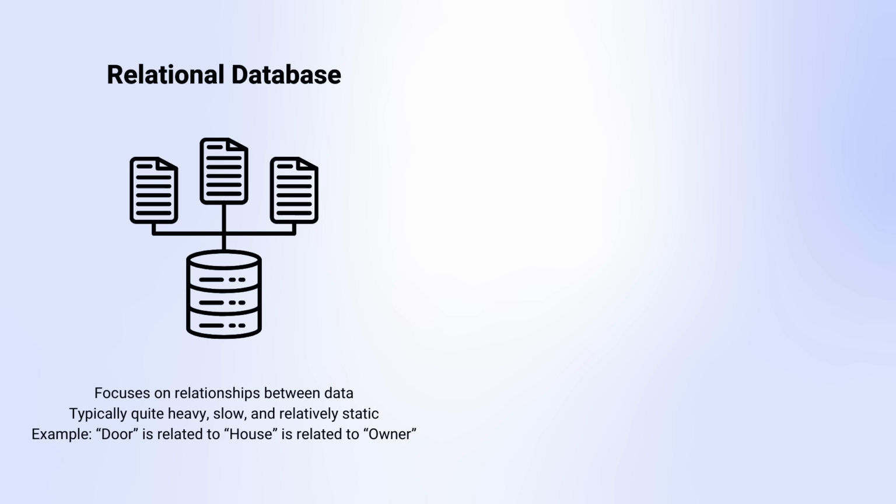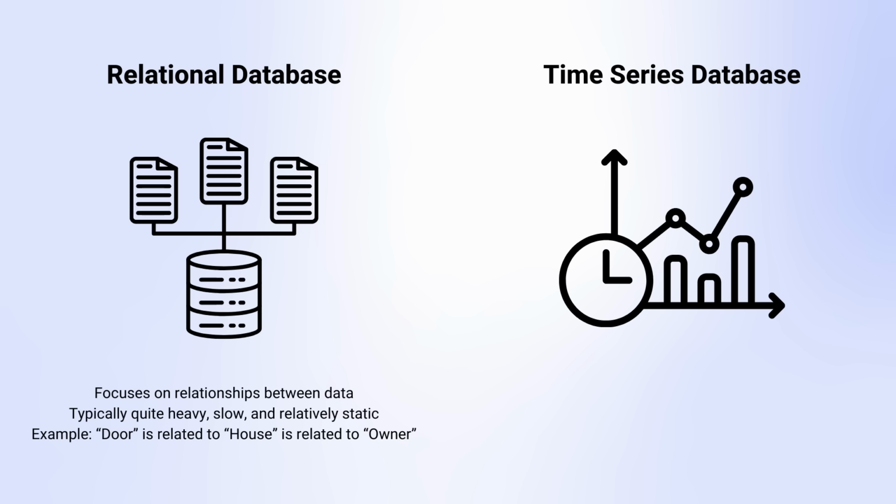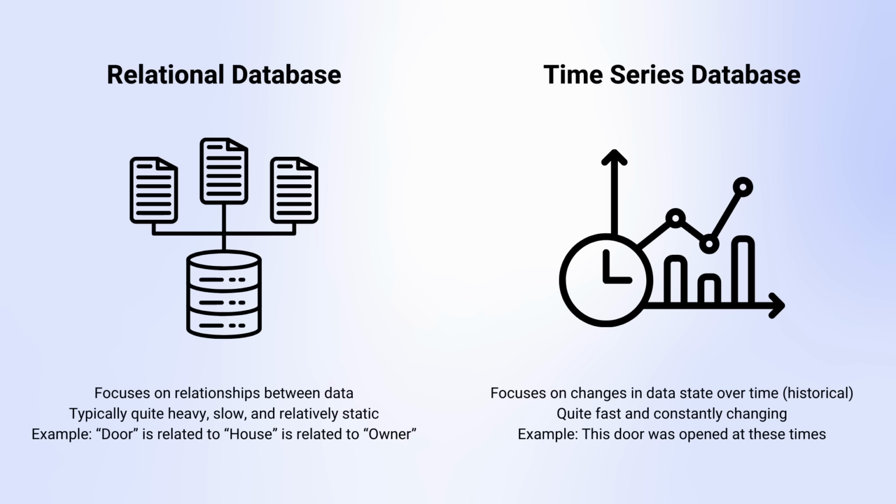Now, an important thing that we should clarify here is that we have both relational database storage as well as time series database storage. Now, there's a pretty significant difference between those two technologies. See, generally relational databases that aren't time series based just give you a view of the data as it currently exists at a slice in time. Time series databases, however, store historical data in addition to current data.